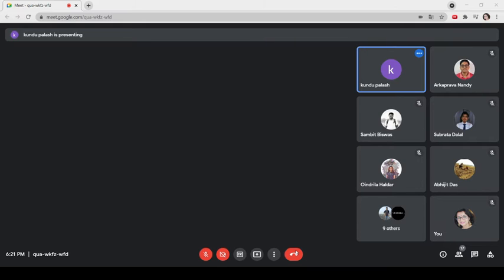Now what is the basic difference between the timer or counter? This is the functional diagram of the timer. Inside this is an AND gate. One input of the AND gate is coming from another register bit, the TR bit of the TCON register. If this bit is set to 1 logically, then and only then the timing signal coming from the basic crystal, or divided by some factor, will pass to the output of the AND gate. Otherwise, if this is 0, the timing signal will not be passed.